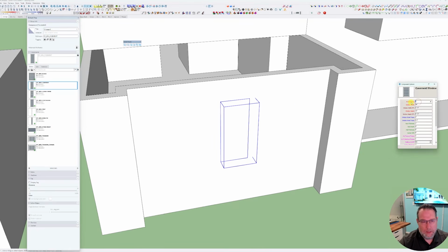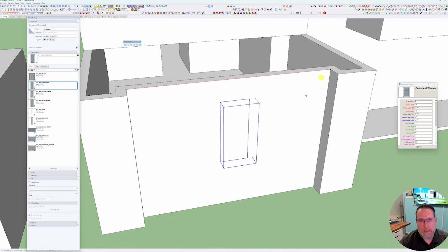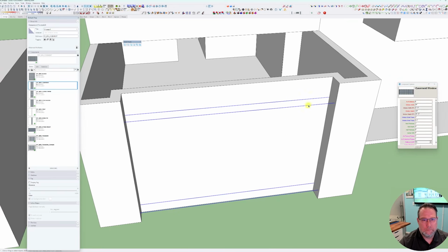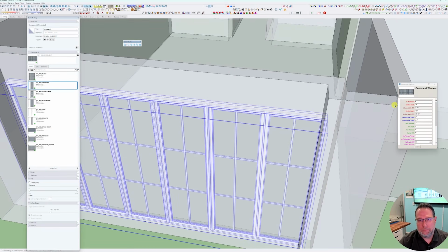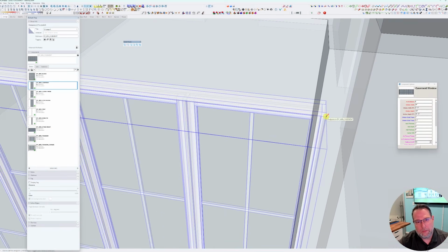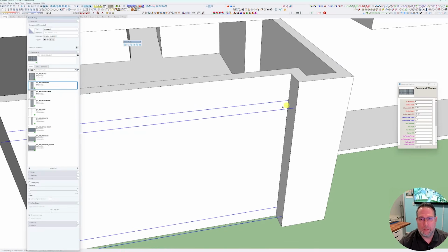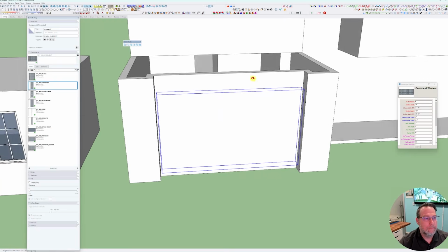So I'm going to make this, let's see here. What is this distance? This is 18 feet. So if I do, let's go 6 3-foot windows that are 10 feet tall. Yep, perfect. I got a little bigger because of frames, and that's okay. We'll just knock this down to like a 34-inch, and that's fine.